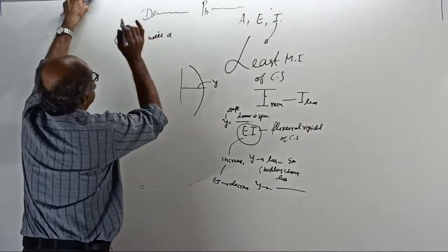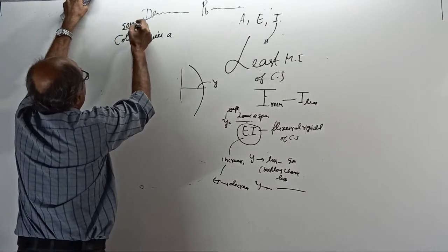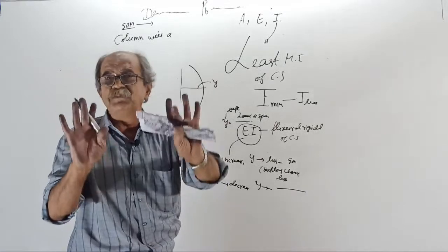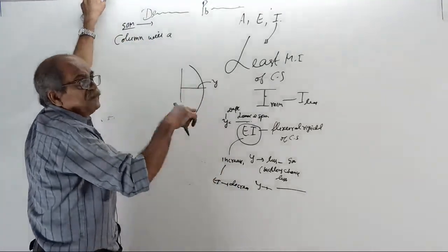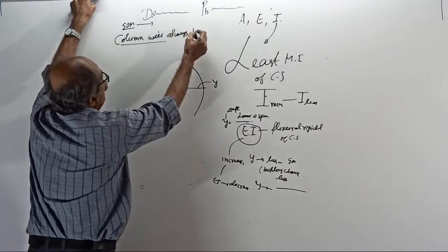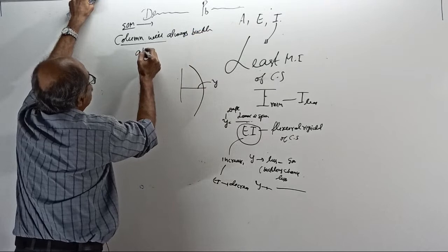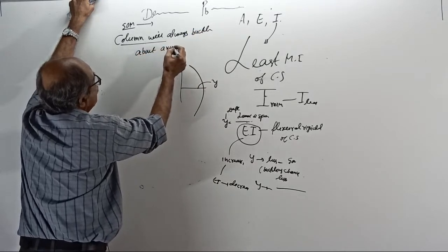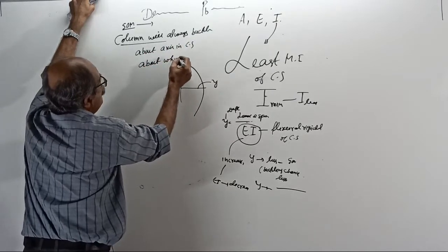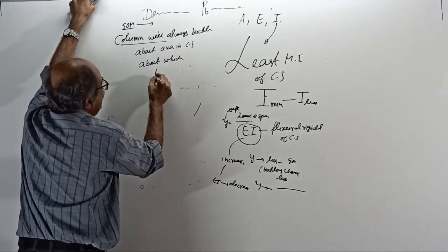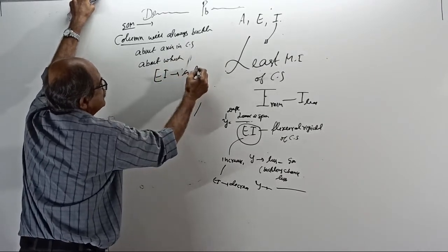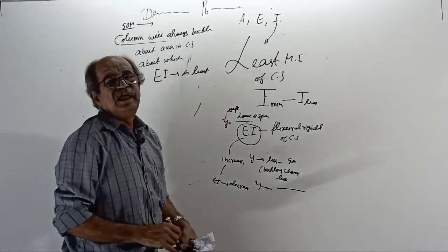From a strength of materials point of view, if the effective length, which will come later, is constant with respect to all the axes, the column will always buckle about the axis in the cross section about which flexural rigidity EI is least. Common sense: where weakness is there, it will buckle.